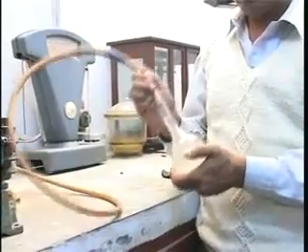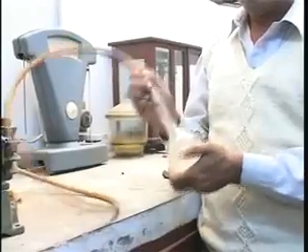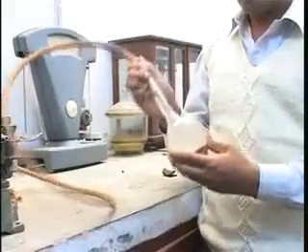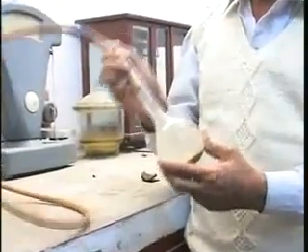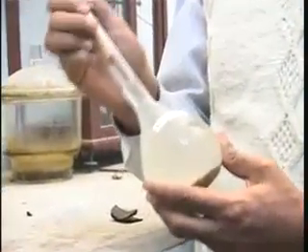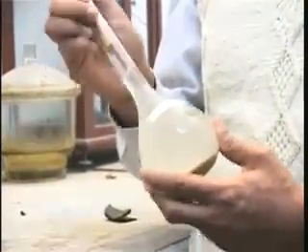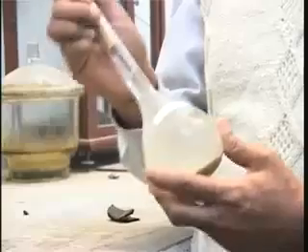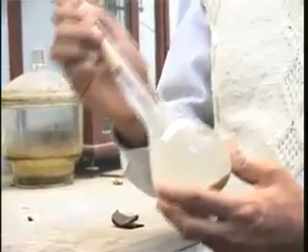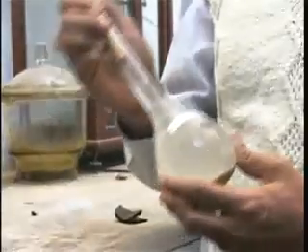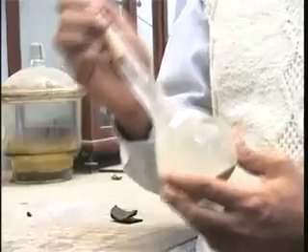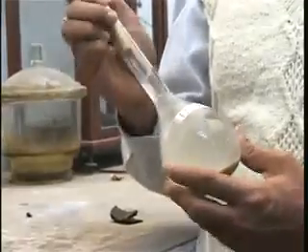Here you see that the soil is kept under a vacuum pump, kept under vacuum here, and that is being shaken by my colleague so that the mixture doesn't have any inclusion of air, because that might, as I was mentioning, introduce some error in the estimated specific gravity of solids.